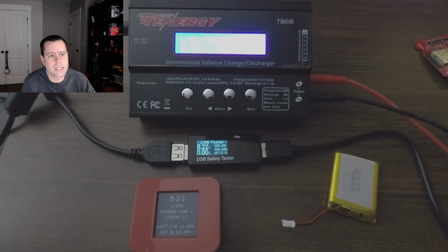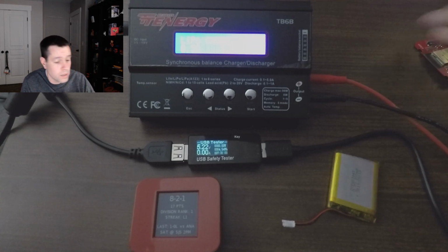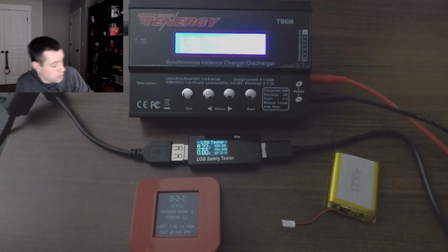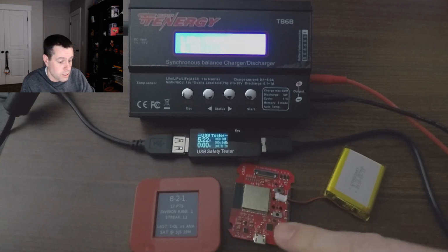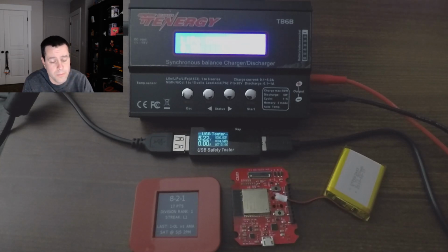Because we're not asking. What I would expect is that the device would never get more than 100 milliamps, because I have nothing on board this device. And I should just put it down here in the camera. Nothing on this device right here that negotiates that higher current limit. It's not going to ask for more than 100 milliamps.